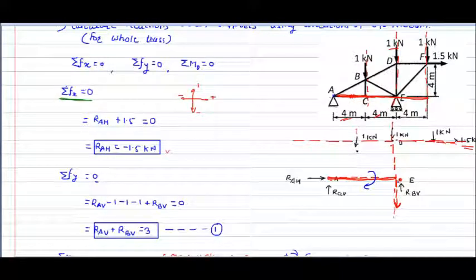That is what is called the line of action. And then from the fixed point, A is our fixed point, from A to this line of action drop the perpendicular. This is our perpendicular distance in case of this force of 1.5 kilonewton. So here that perpendicular distance is nothing but 4.